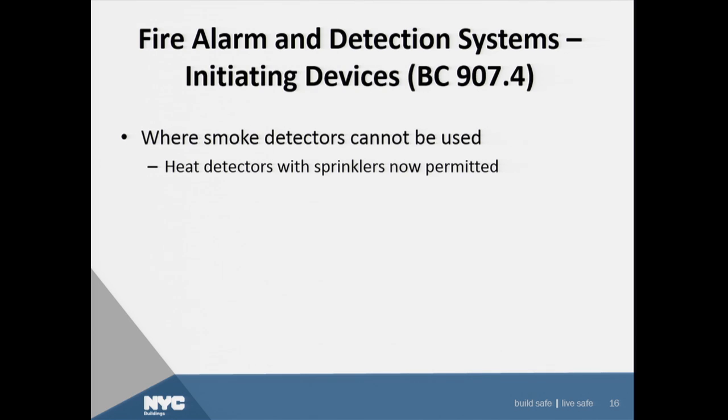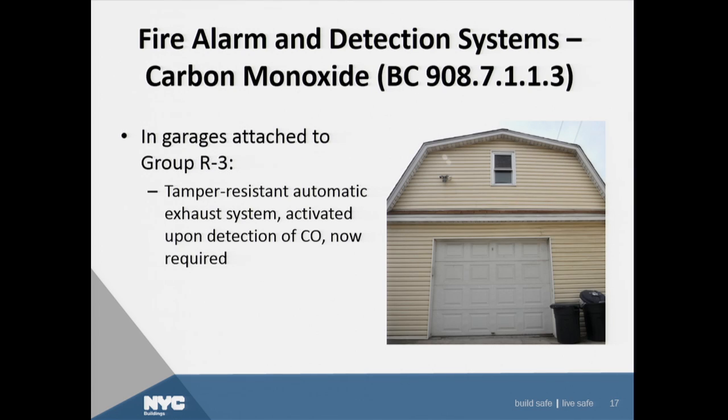Okay, so there's a new provision also that makes it a lot easier to substitute a heat detector for a smoke detector in a building, if it's something where accidental activation could be caused by the types of equipment or the types of uses in the room. And here's a provision, and we will be working on some guidance soon with a buildings bulletin to describe what this is.